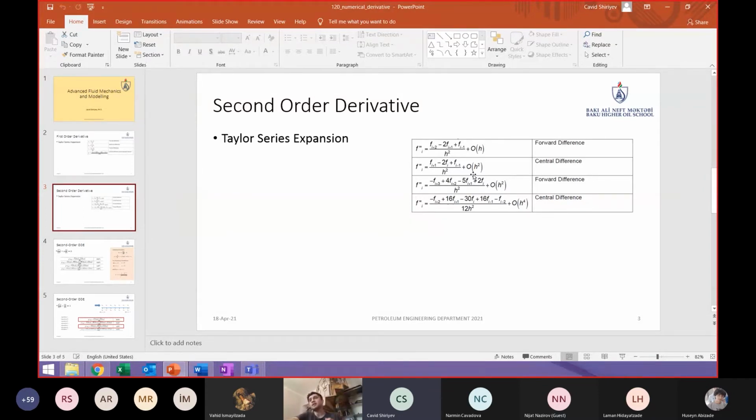And the other thing regarding the numerical solutions is that in the simple scenario, the single phase flow, most probably we are going to go with the implicit solutions, because implicit solutions are more robust than the explicit solutions. We are going to introduce why we are using this implicit term. Basically, it's only because we are using the n+1 time knowledge in order to calculate the n+1 time. Otherwise, in the explicit solution, we are using the n time step knowledge to calculate the n+1.